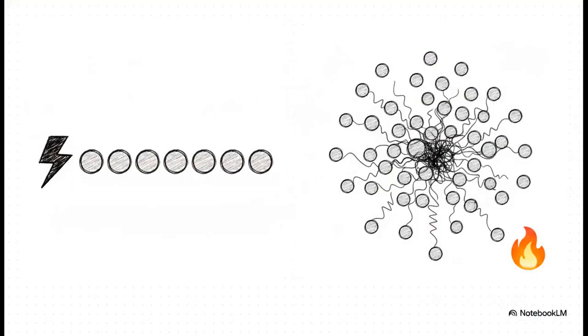Okay, so let's dive into this microscopic world where particles are in a state of constant, random Brownian motion, totally fueled by thermal energy. Basically, at any temperature above absolute zero, particles inside a semiconductor lattice are constantly vibrating, crashing into each other, and wildly changing direction. Now, there are two main ways to actually move a charge here: drift and diffusion, and the contrast between them is huge. Drift is basically a forced march. You apply an electric field, and particles are deterministically pushed in one specific direction.